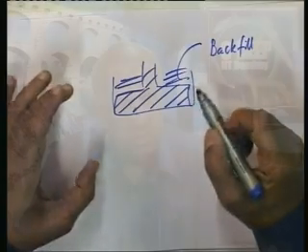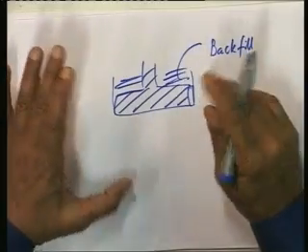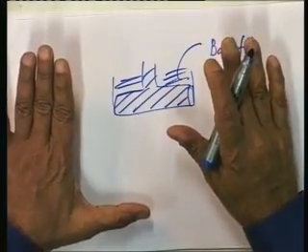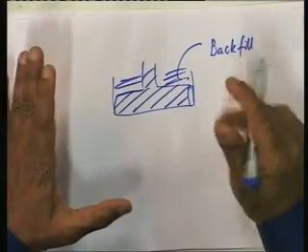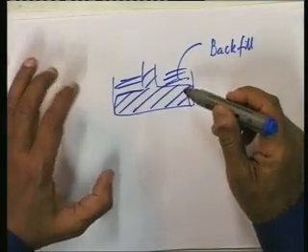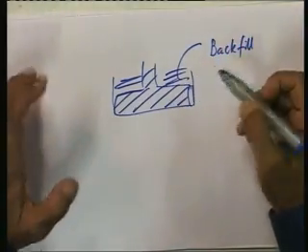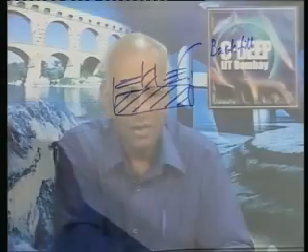It is possible to take this into cognizance, but for illustration of the computation, I shall be ignoring the increase in stress arising due to concrete. I shall take the stress as purely that due to the soil, but the increase in stress due to replacement of soil by concrete can be very easily taken into account in the same procedure.